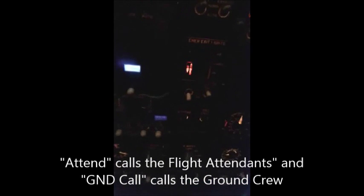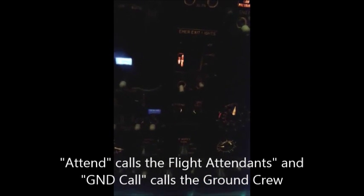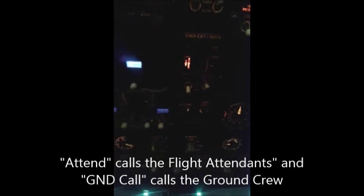Okay, moving up, you have the wing and engine anti-ice, window heats. Going over here, interior lights for the circuit breakers and the panels, equipment cooling, emergency exit lights, and they have the fasten seatbelt sign. Attendant call, that's the ground call, so if the flight deck wants to call the ground, they can call it. Wipers, left and right. Electrical panel.